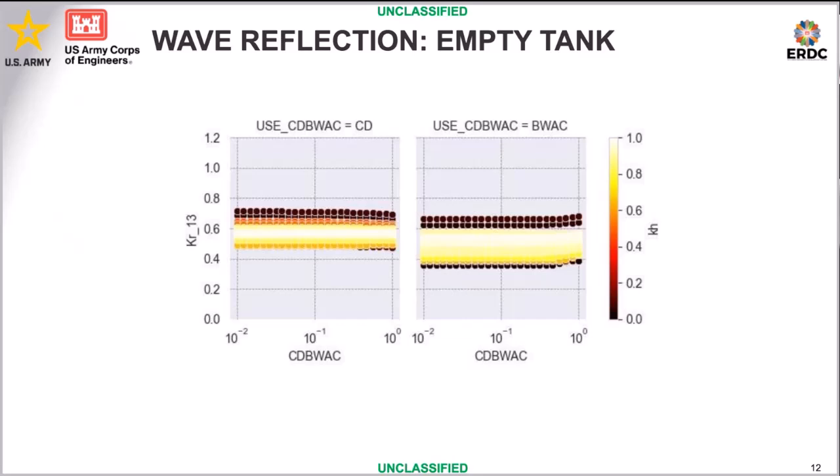And that band narrows for the higher KH values. Higher KH is your longer wave periods in deeper water, versus lower KH is the full range of wave periods but in more shallow water. So that's what we're seeing from dark to light. There is even some level of trend or no trend from what I'm seeing.